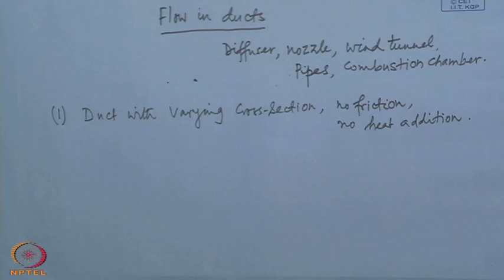Earlier we have derived the area velocity relationship in a high speed flow, and we have seen that in the subsonic part, as area decreases, flow velocity increases. However, the rate of increase in compressible flow is faster than in incompressible flow, where area and velocity obey the clear inverse proportion law.